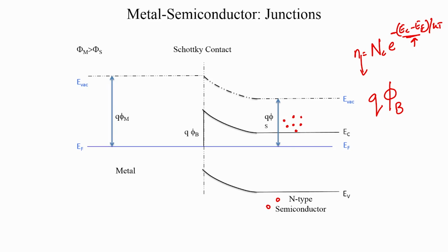Now, think of the electrons in the metal. Let us say the electron in the metal has to get past and get into the semiconductor. What does the electron see? It sees a massive barrier. So, as we discussed earlier, the band bending diagrams are drawn such that the higher potentials lie at lower points.